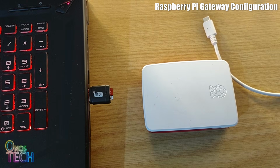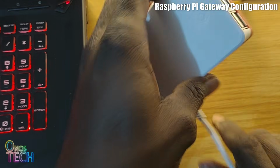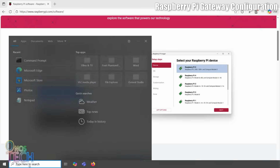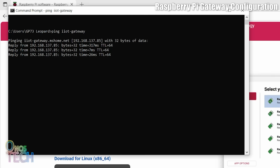When the write is complete, remove the SD card from the card reader and insert it into the Raspberry Pi. Power it up and allow it to boot up for about 60 seconds. Open Command Prompt on your computer and enter the command ping IIoT-gateway. This is to confirm the Pi's connectivity to the network.